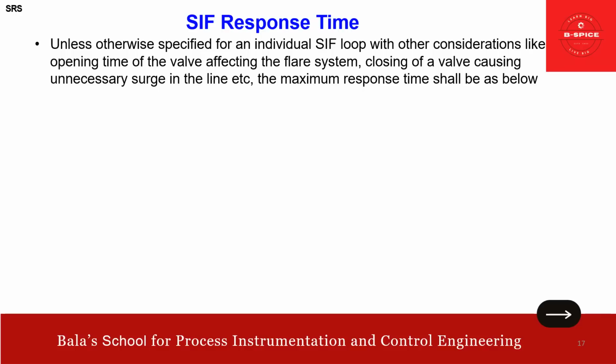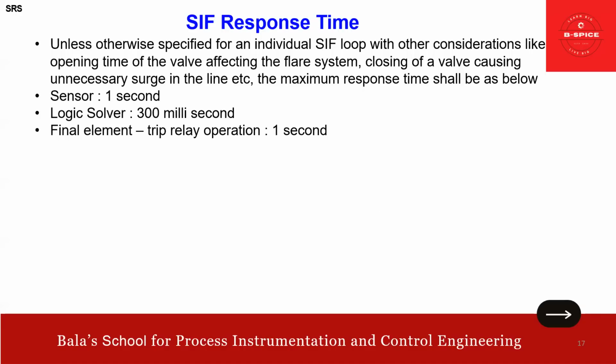Unless otherwise specified for an individual SIF loop with other considerations, like opening of the valve affecting the flare system or closing of a valve causing unnecessary surge, the maximum response time will be as below. For the sensor, it is 1 second. Logic solver, 300 milliseconds. Final element, 1 second. So this is the SIF response time.